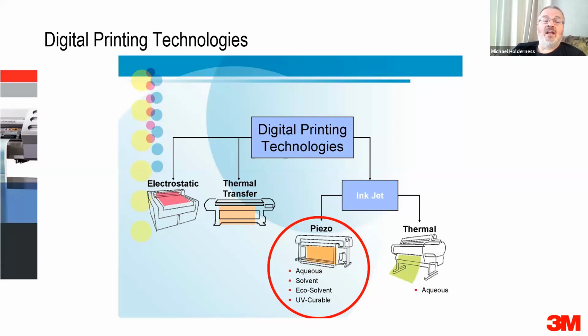That was basically an electrostatic printer. It took toner particles via a carrier medium and then fused them onto the vinyl. Quite a complex process, but it worked remarkably well. The beauty of the electrostatic printer is it produced an incredibly durable graphic. The graphics produced on there could survive on aircraft, and they lasted years and years. The detail wasn't very high, so the dots per inch were fairly low, but they did a really good job for aircraft marking.